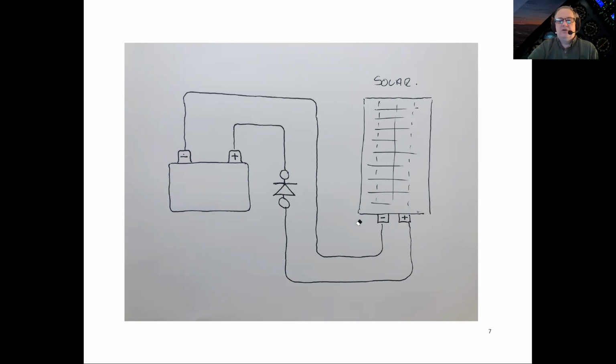So solar collectors that are actually in shade, where there's a difference, like if you have an array of several panels and one of them is shaded, there can be enough difference where it will actually start to reduce the amount of charge that the other panels can produce. So these diodes are an important part, in many cases actually internally wired right with each cell.